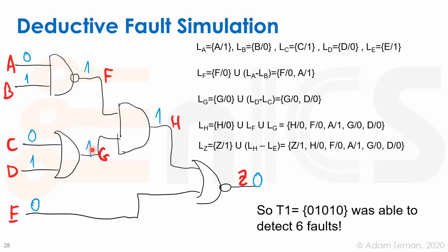There's a difference between debug and failure analysis, and both of them may require such analysis. Failure analysis means that you're manufacturing your chip, you have 80% yield, but the 20% that are failing all have some failure mechanism which is repeated. Then you do this kind of analysis, but again, if you have a compressed or an optimized set of vectors, it would be difficult to find it. Sometimes you maintain a set of optimized vectors, and you also have a set of non-compressed, non-optimized vectors that help you detect the exact problem.